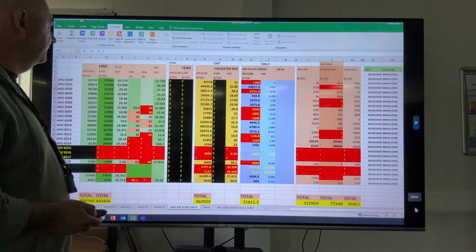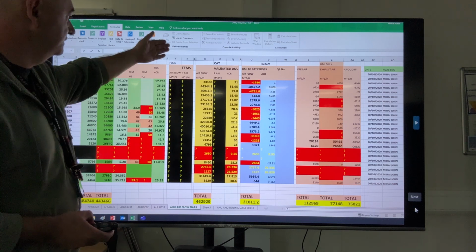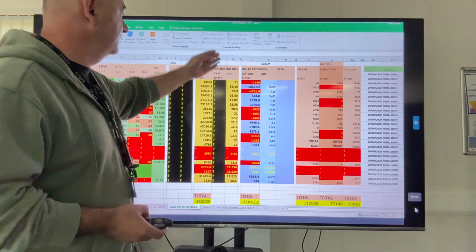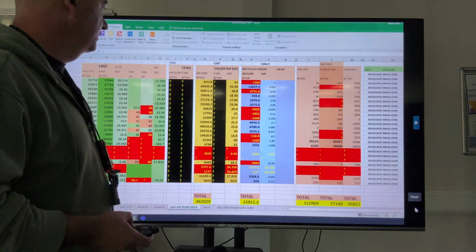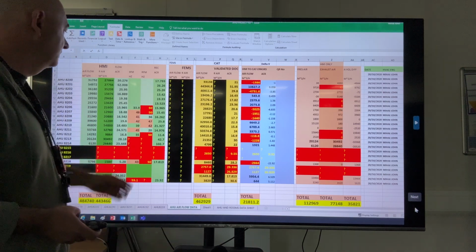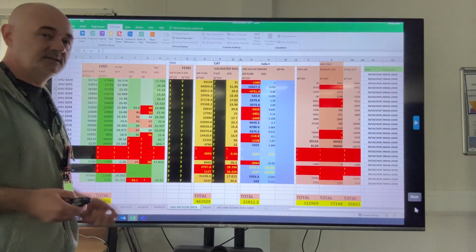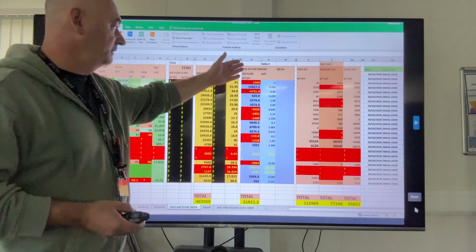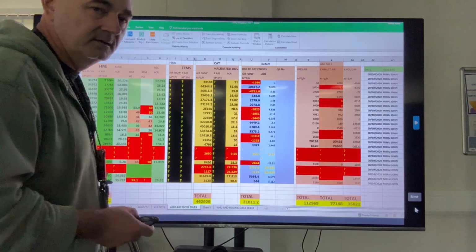FEMS tells me nothing. If you look, FEMS question marks. You see, it doesn't help me too much. I use the validated documents to check the cubic meters per hour. It's like a CAT measurement against the SCADA, and even if I've been told in the past SCADA is not validated, SCADA is the one that provides the airflow. FEMS reads it, but in my case reads nothing, and we have here the errors between these readings. Can you imagine? Everything on red represents an error.